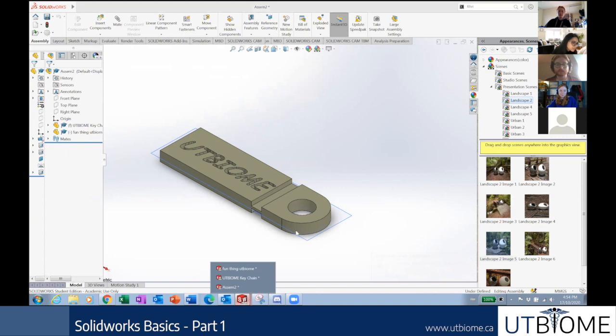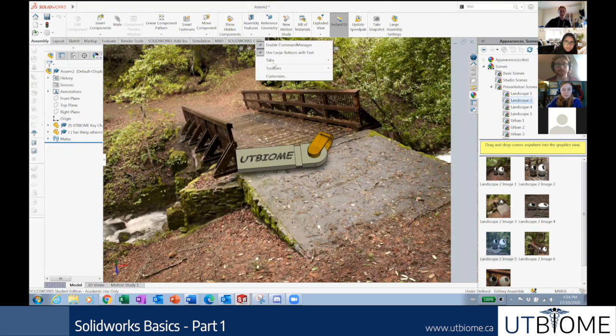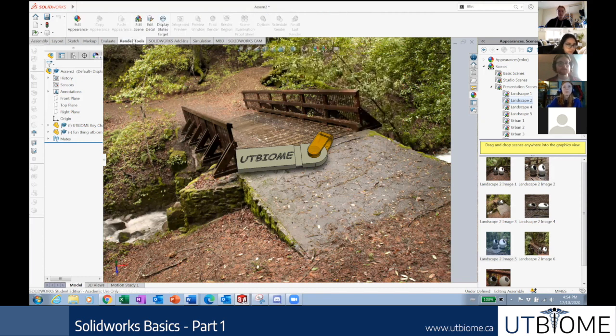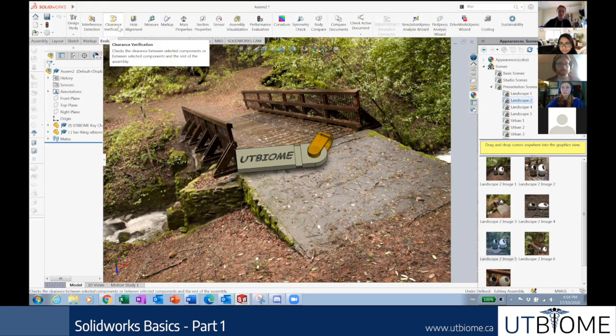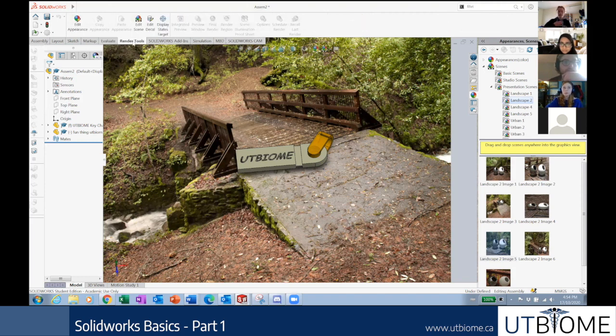I don't know how this is gonna turn out because there are certain things I normally try to set up properly. I go to tabs. I added the render tools in. So I'm gonna go to render tools, and render tools requires a few things. I'm first gonna go to evaluate. I made my screen very messy. Give me a second just to find it. Here it is. Okay, so you go to SolidWorks add-ins actually. You click PhotoView 360. SolidWorks may change this so that this isn't a necessity, which I'm sensing is the case.